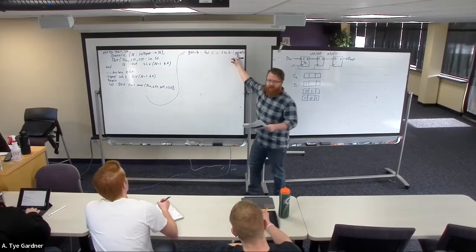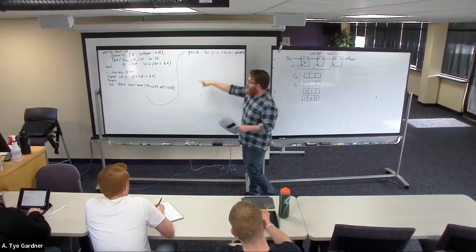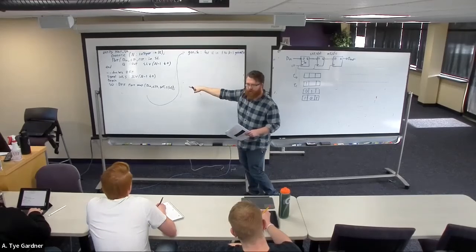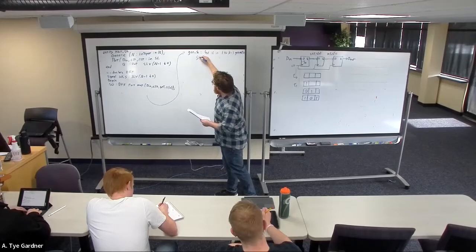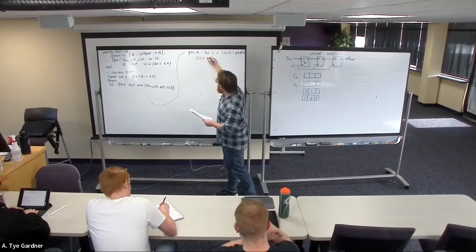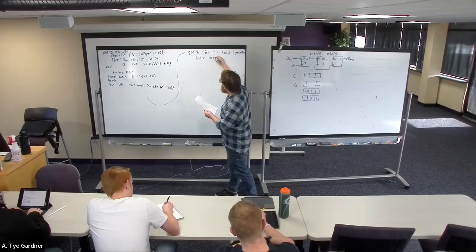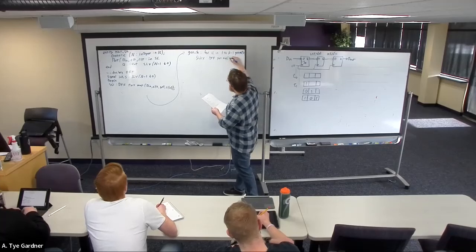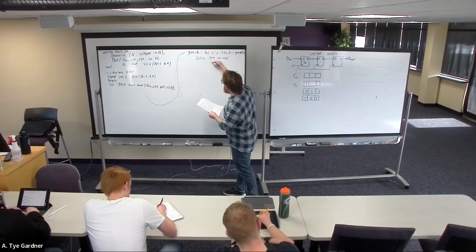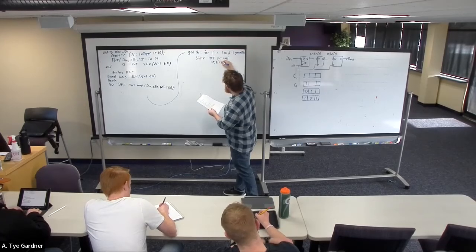Sorry, ran out of room. This says generate. So for I in 1 to n minus 1, I don't want to do 0 because I already took care of the 0 location over in this first one. I'm going to say shift X, give it a name, the flip-flop, a port map of, I'm going to put the port map down here, int S at I minus 1.